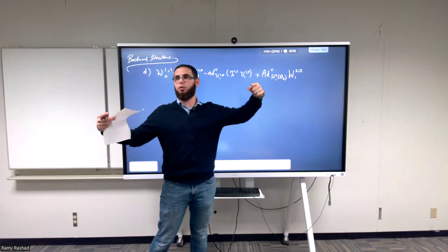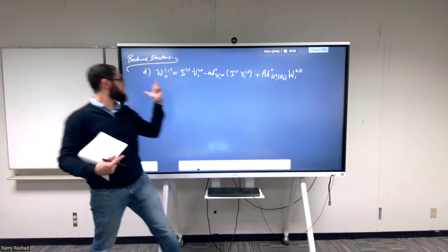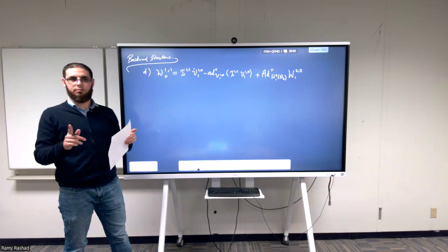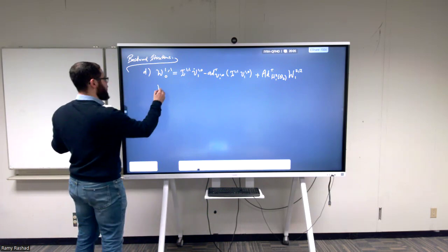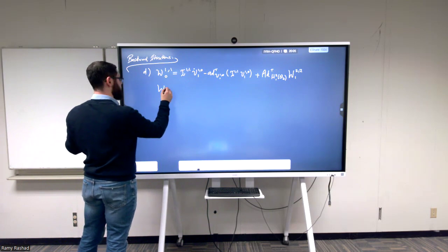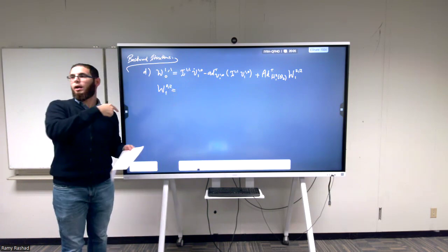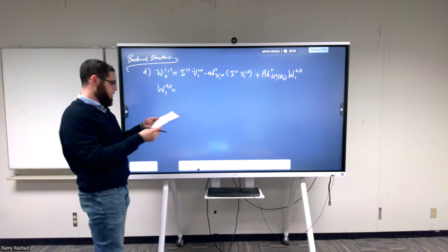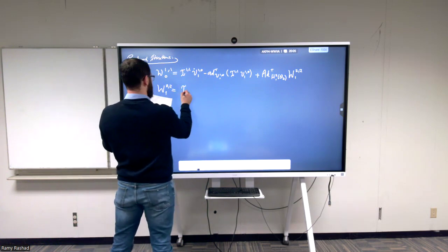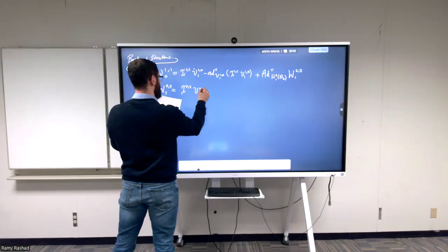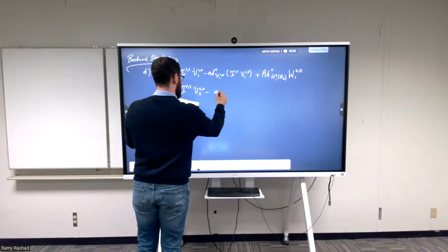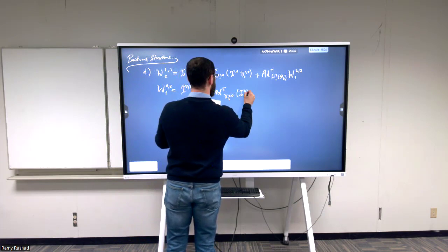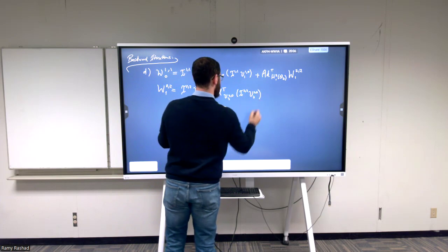So 1 is in between 0 and 2. This is the reaction from the 2 link, and this is the reaction from the 0 link. And we're calculating here, this is for the link 1. Questions? Okay. When we do the same for the 2 link, the 2 link is connected to the 1 link, but not with anything else. So there's nothing else after it, because it's the leaf of the tree. So we have here I2 V2 dot minus the joint transpose of 2 0, I2 V2 0.